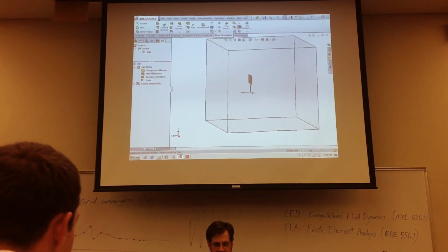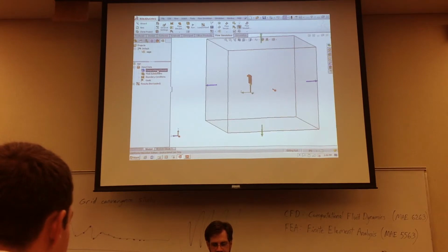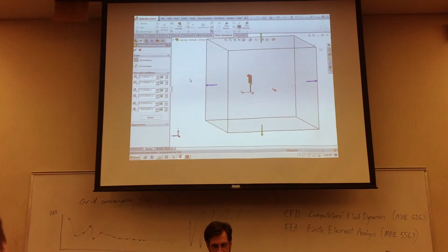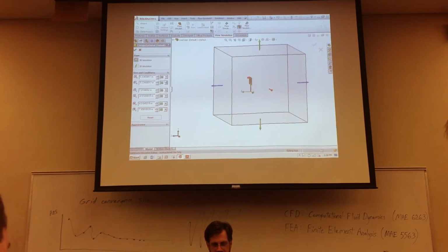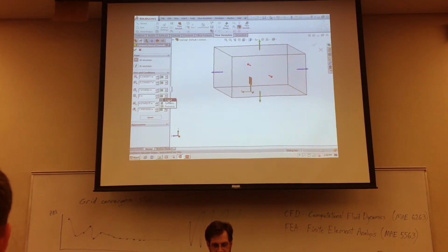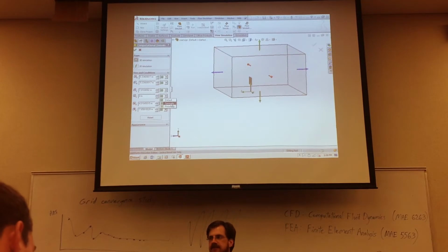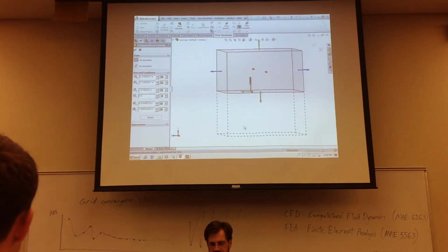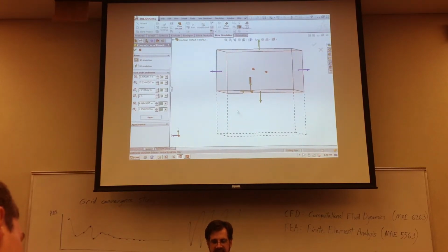The way we do this is go over here to the computational domain, right-click, and say Edit Definition. Okay. So this gives you the location and the type of boundary for each of the 6 sides of this domain. And in the y direction, we want to move this lower y boundary to 0 meters, and we want to change its type from the default to a symmetry boundary. Okay. You can see what that does is kind of give you a dotted line mirror image representation of this same domain existing underneath the sign.